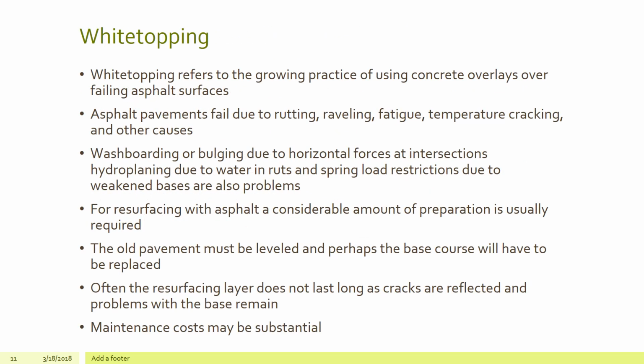Whitetopping refers to the growing practice of using concrete overlays over failing asphalt surfaces. Asphalt pavement fails due to rutting, raveling, fatigue, temperature cracking, and other causes. Washboarding or bulging due to horizontal forces at intersections, hydroplaning due to water in ruts, and spring load restrictions due to weakened bases are also problems that we face within our paving processes, or environmental concerns that attack our paving surfaces.